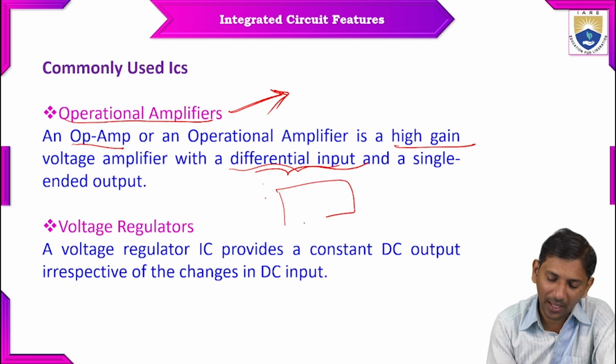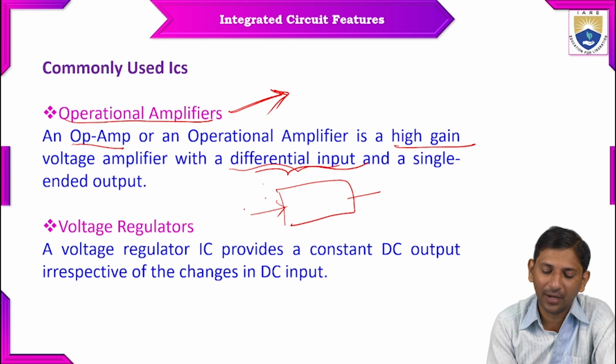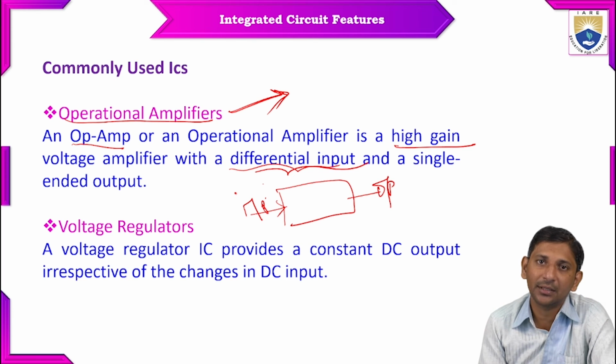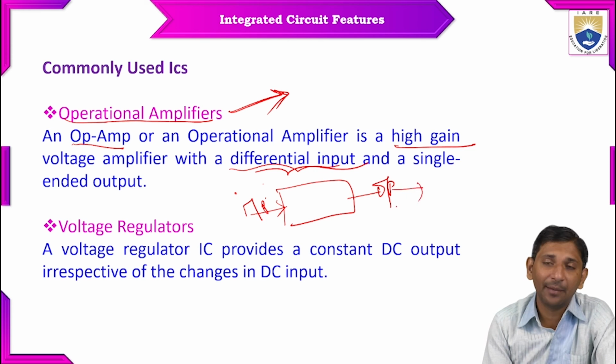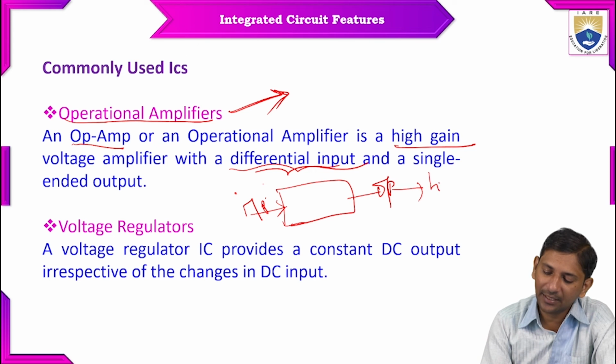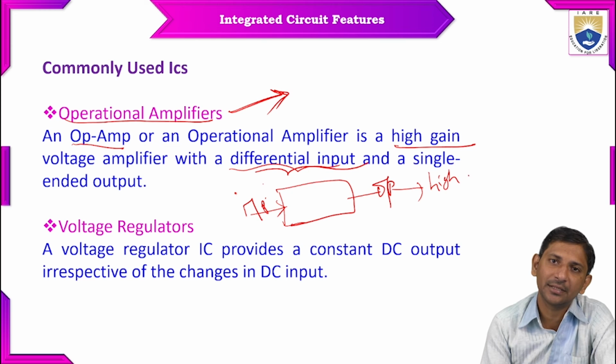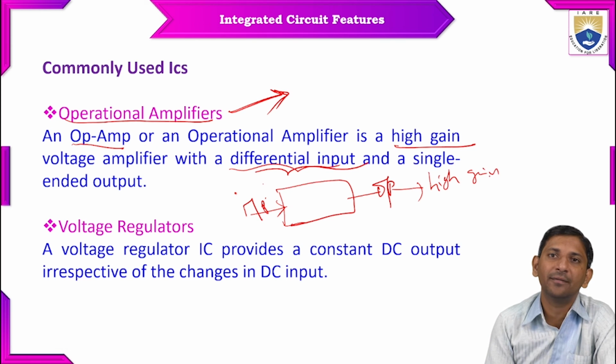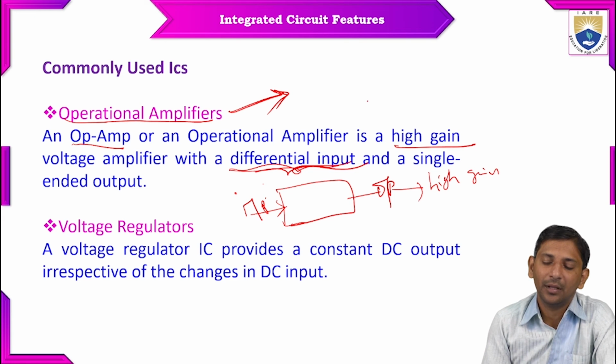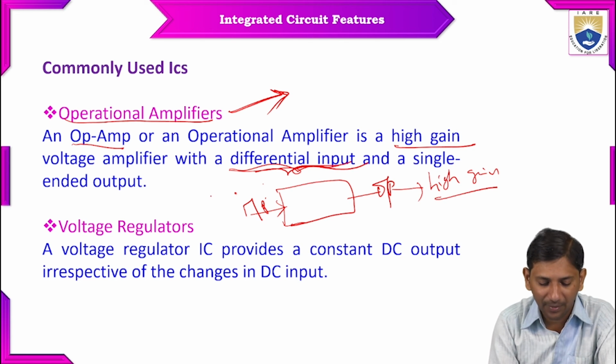Now let me discuss this one. The operational amplifier is going to perform multiple operations like adder, subtractor, filter, converter, amplification process, oscillator, signal generation, etc. All of these can be performed using a single chip with high gain and high output voltage. Differential input means we have two inputs. The difference between those inputs gives an output through the amplifier operation.